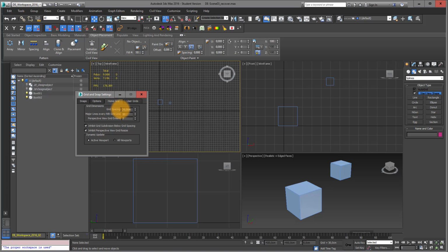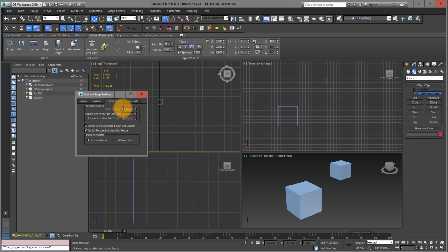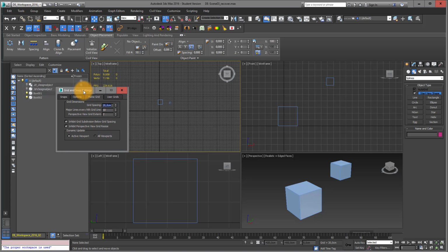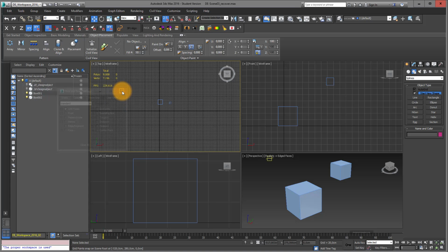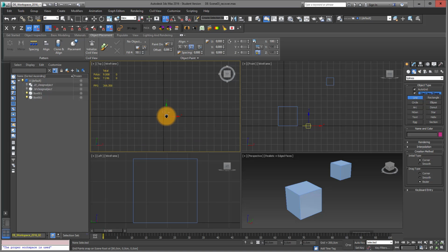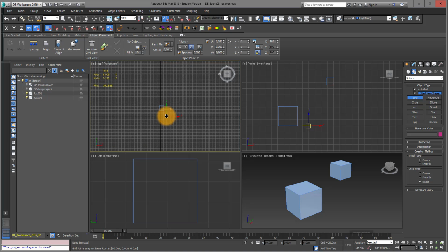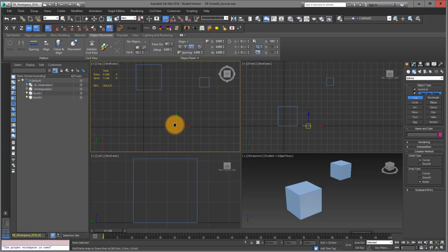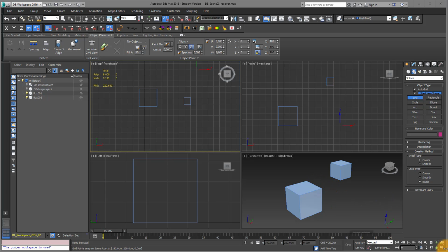By default, I think the home grid is 10 centimeters, and I just change it to 20 centimeters. Sometimes I use this grid function, for example, to draw lines. I deselect vertex, endpoint, and midpoint, choose my line tool, and move in a little bit. You can also see that it starts to abstract if you move out, so there are different appearances regarding the scaling.